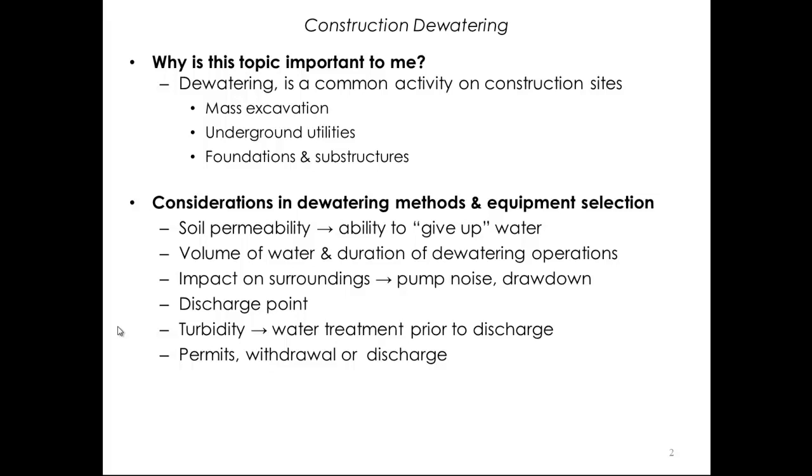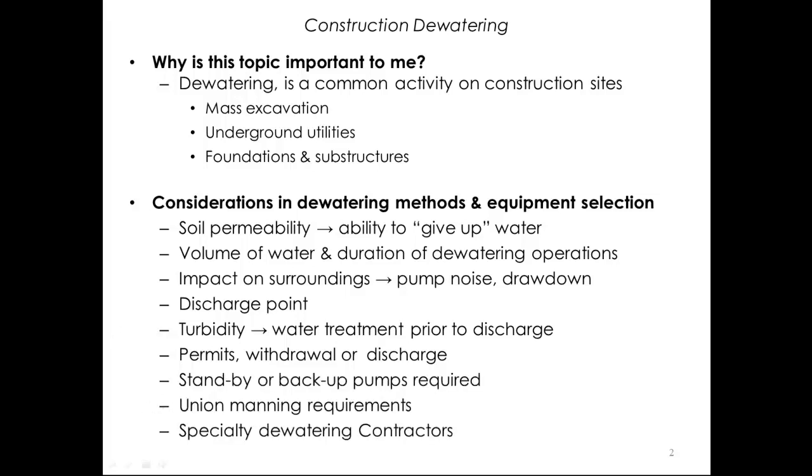Huge issues can be: 1, where to discharge the water, and 2, what to do if the water is turbid. At this point, you should just know that there are methods to remove suspended solids in water to meet discharge requirements. Additional things to consider: will backup pumps be necessary? What would happen if the pumping equipment would stop due to a mechanical problem? Is the risk of the excavated area flooding sufficient to justify the cost of standby or backup pumps?